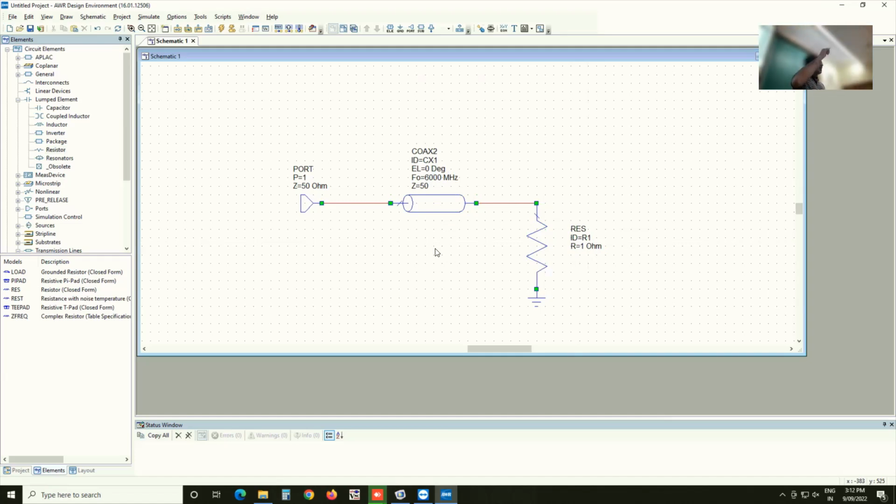So remember this e to the i beta z factor which had come, that basically tells you that the voltage wave will develop a phase as you go along the transmission line. So this is basically telling you that in degrees. And the convention again is that when you go one full wavelength, it is 360 degrees. So 0 degrees means it is basically not there.